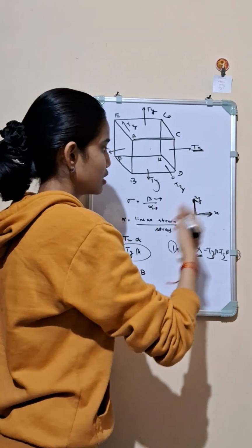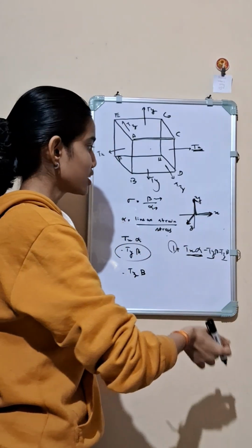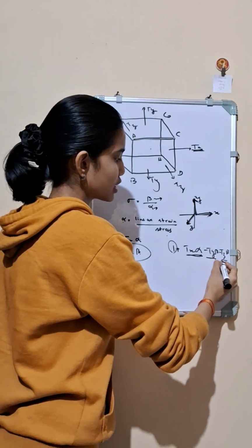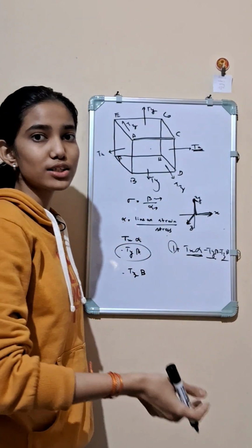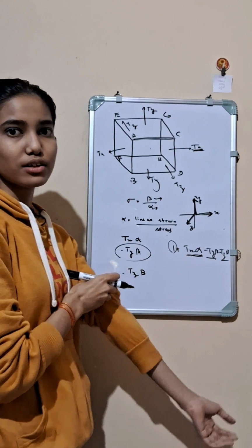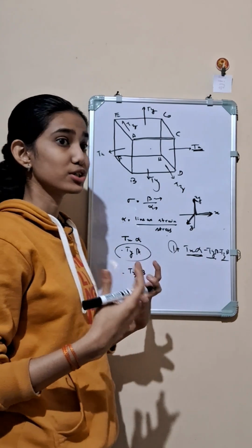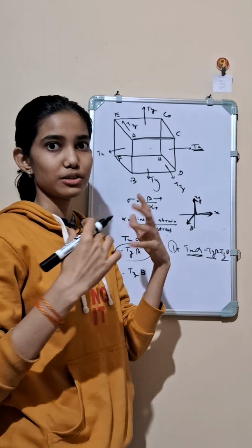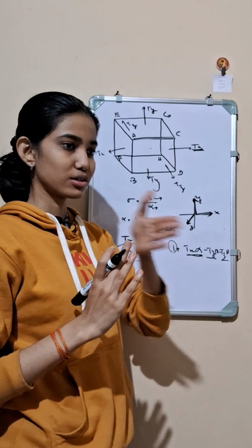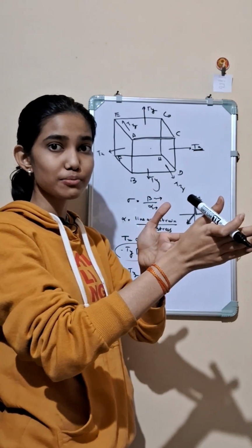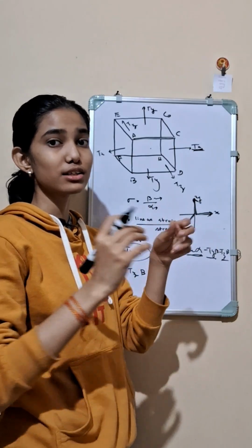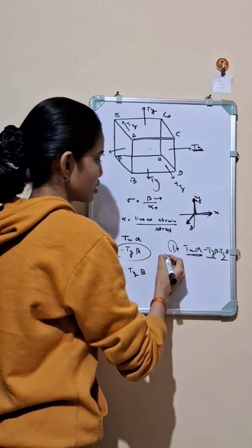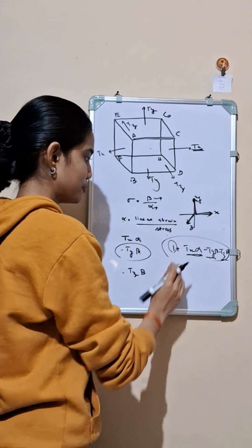The increment is due to the tensile stress along the x axis, and the decrease is due to the perpendicular stress. Basically, from Poisson's ratio it is clear that the length along the direction of the stress increases, but the length perpendicular to the stress decreases. So this is used here.